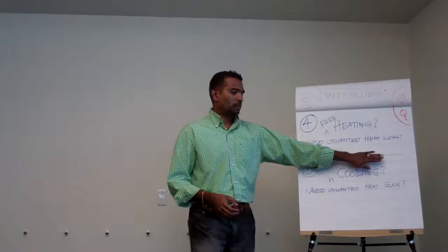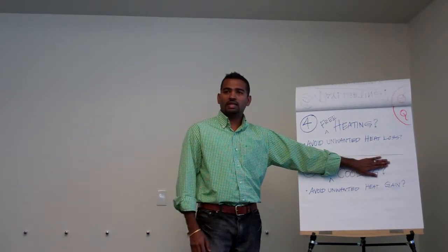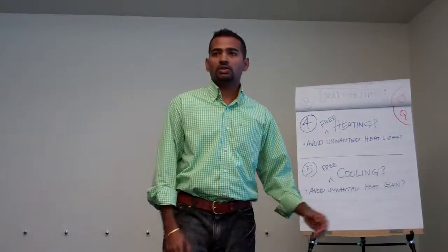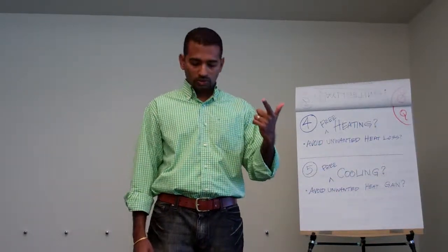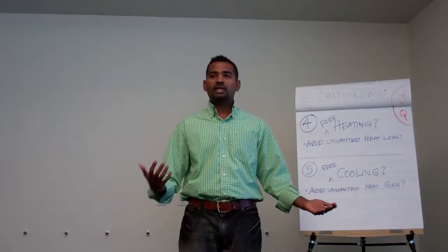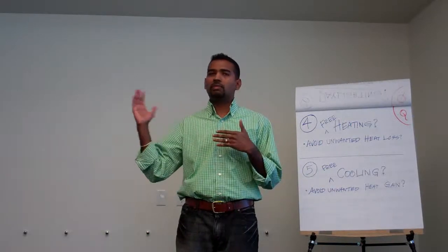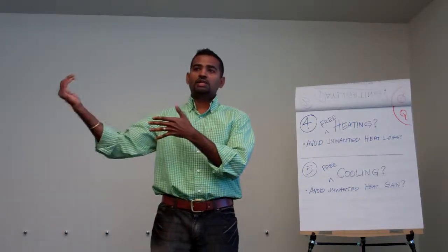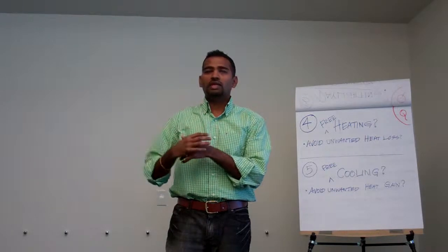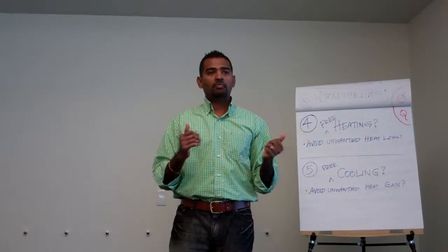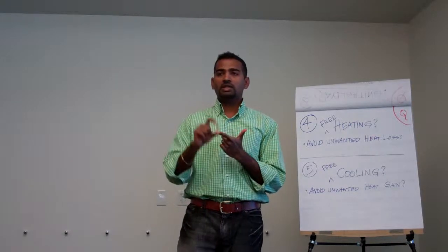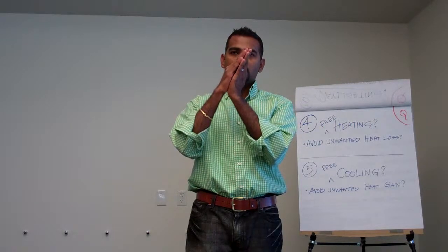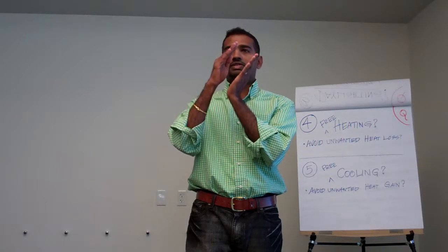So if our client says, all right, let's take this risk, then you kill the boiler in Phoenix and go with this design. The other issue is, we can hand calculate how much thermal mass we need based on the aperture to heat the building so that it releases that heat during the heating season. We can do that. But the clients have to be comfortable with that, because any passive cooling strategy or heating strategy will have this climate comfort slightly stretched.